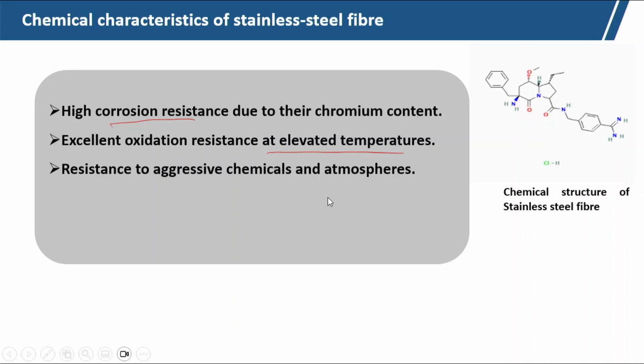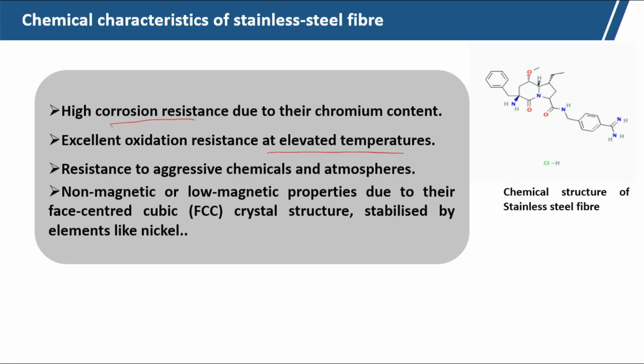For long term application we can use this stainless steel fiber, where it does not corrode or oxidize. So, for external application we can use this fiber for specific applications. Stainless steel fibers are non-magnetic, or sometimes low magnetic, due to their face centered cubic, FCC, crystal structure, stabilized by elements like nickel.